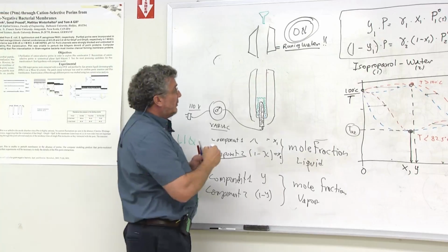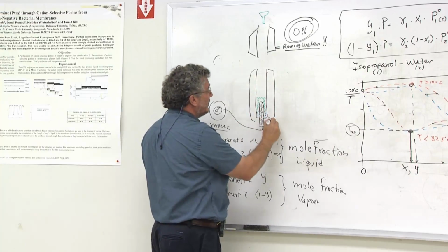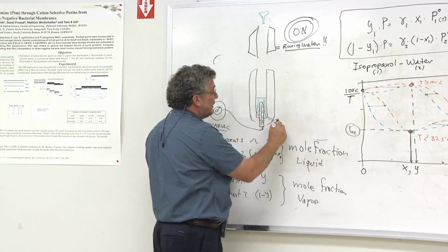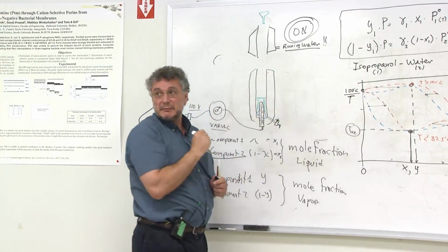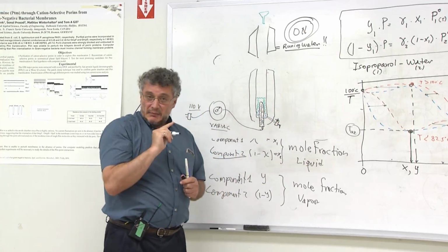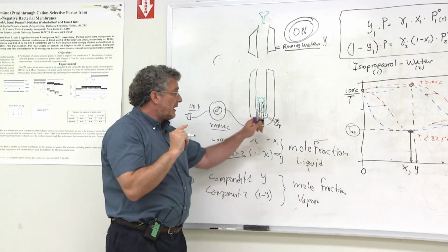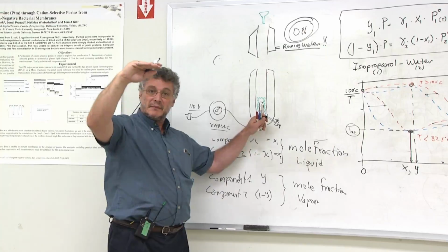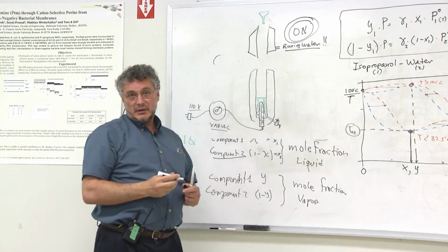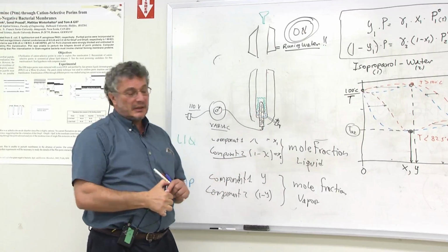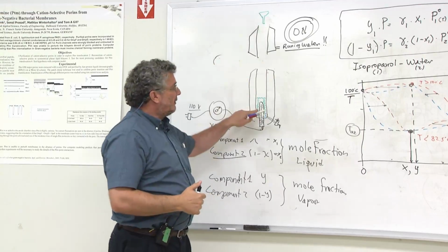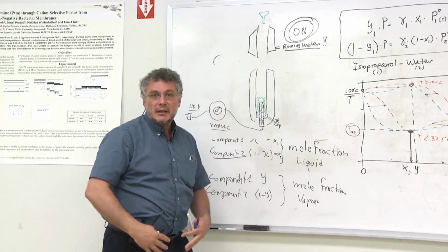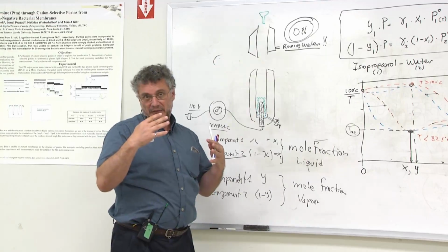So how do we sample this? Well, there's a little tube here where we can take samples of the liquid, and we can also use that to empty it. When it's empty, if this has not been unplugged and cooled down, its temperature is going to start to increase. And if you have a mixture that has lots of isopropanol in it, and you threw it from here, all of a sudden it's going to absorb heat instantly, it's going to flash up and evaporate.